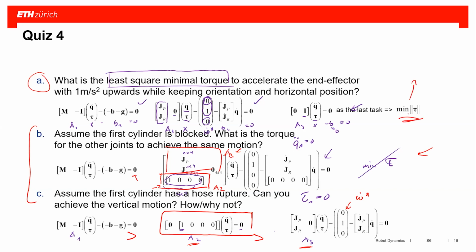But instead of optimizing the joint torque, I can also have another task which drives my Q towards a Q desired, so a nominal configuration. So I decide my Q double dot to be such that I have a potential field around the desired Q, and then it will try to stay as close as possible to a nominal configuration while fulfilling the end effector task. And that's exactly what happens in avoiding collisions of individual actuators, joint range limitations.